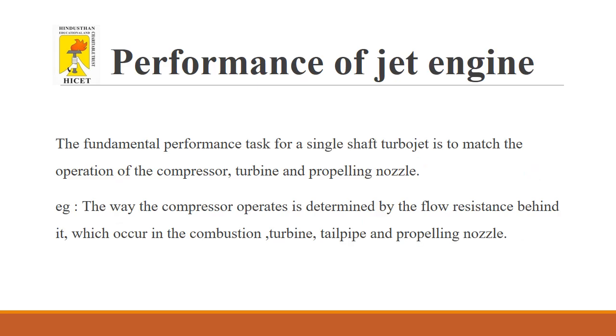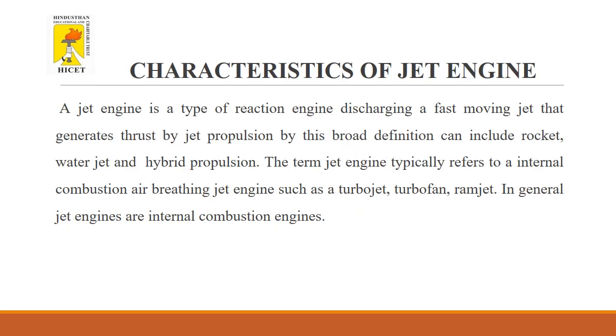The performance of a jet engine. The fundamental performance task for a single shaft turbojet is to match the operation of the compressor, turbine and propelling nozzle. That is, the compressor operates at a point determined by the flow resistance behind it, which occurs in the combustion chamber, turbine, tailpipe and propelling nozzle.